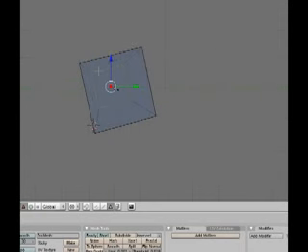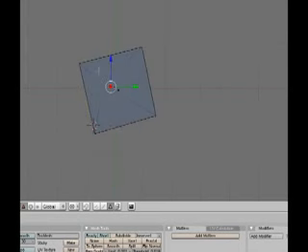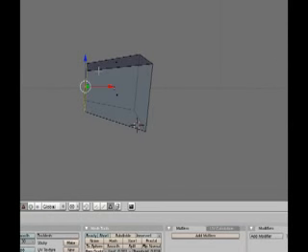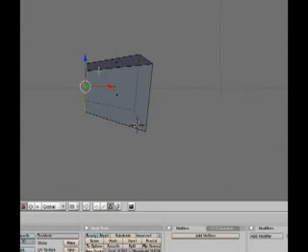You can see from the different angles from the numpad. And if you're ever changing your views in the numpad and they don't look quite right, push 5. 5 actually changes a few different views.